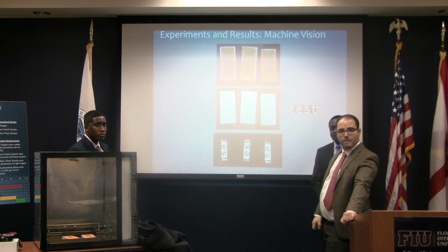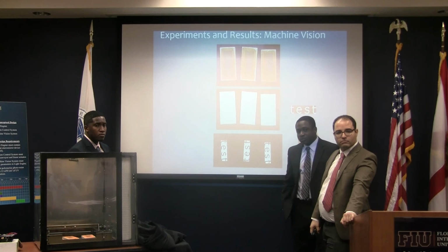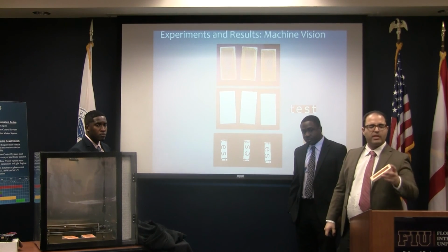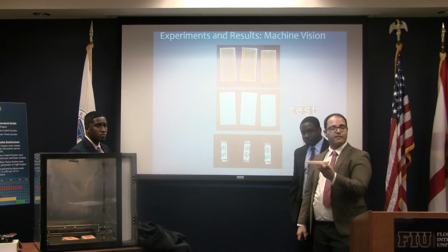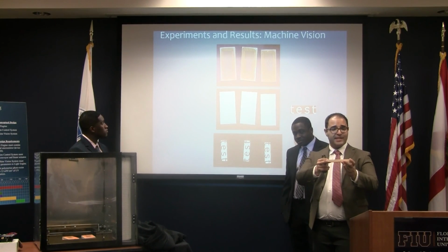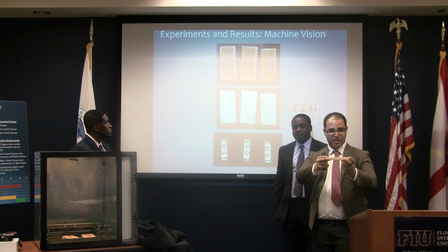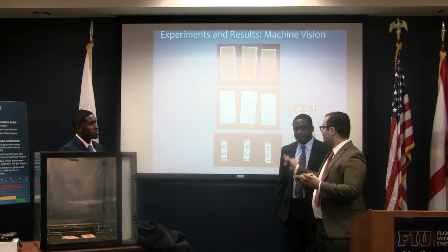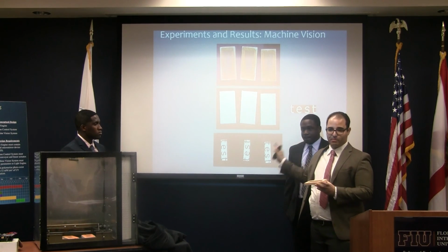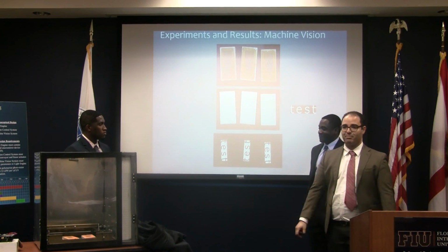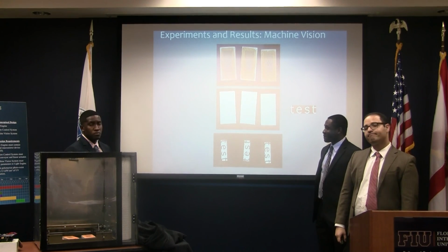I guess the problem is, what if you're printing on a material that is not symmetric and has an actual orientation where you need a certain orientation? Yeah, that's a good question. In this case, you have rectangles. What you would do is take the frame and place it on the machine. And then if there is an orientation problem, you could adjust it on the machine by loosening it and rotating it a little bit. But I assure you, this would not affect the final exposure. I have 10 years experience in the screen printing industry. It's not a big problem. So I'll follow up. Sure.